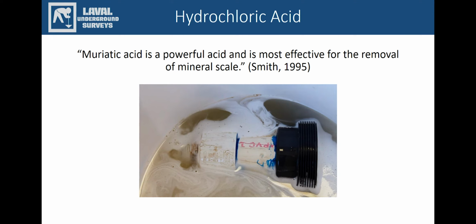There can be a lot of time wasted if your pH is spent downhole after 10 hours and the well ends up being off for 24. This saves you time and your customer time and money from having to do the treatment a second time on a later date. This video shows what mineral scaling looks like when hydrochloric is introduced into a bucket.